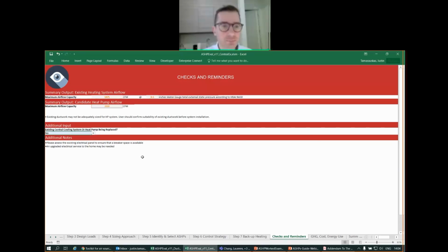And then it'll just provide a little bit of a summary of your backup size as well. Finally, we'll go to the checks and reminders page. Here, this will provide you with some additional things to think about during your installation. In this particular case, with the heat pump I selected, I purposely entered a really large maximum airflow capacity so that I could show you that the tool will compare the two values and then say, hey, maybe you should think about the capacity of the ductwork or examine that aspect a little bit more in detail.